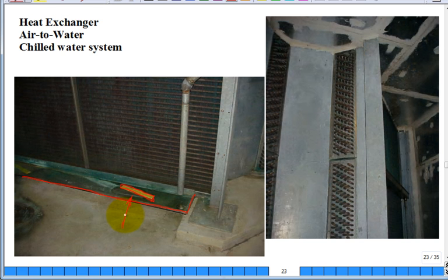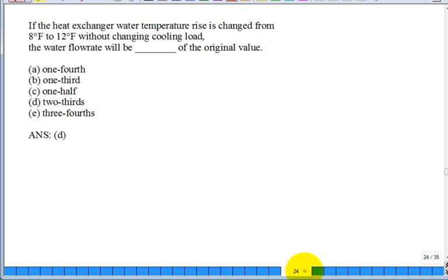A lot of times they also have UV lights, ultraviolet lights, like in a sun tanning station, but they're always on and they're very high and powerful. If they have a UV light, sometimes you really can't tell that they're on. There needs to be a kill switch that's triggered with the door. You never want any worker to go in there and not know that the UV light's on. They'll just get burnt. But it's very effective at killing things and keeping your coils really clean, the UV lights. All right. So we want to talk about that heat exchanger.